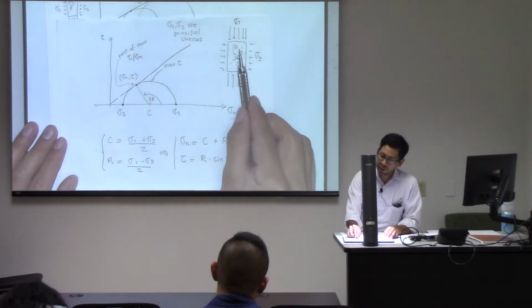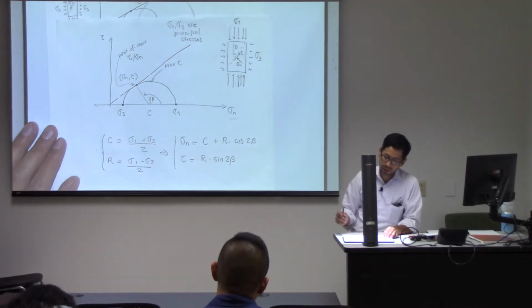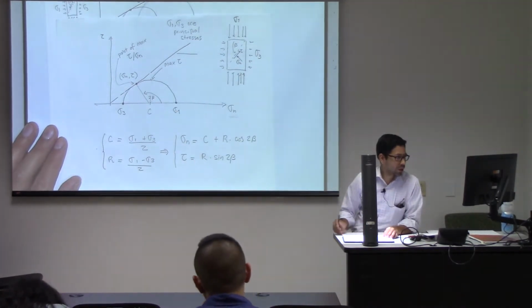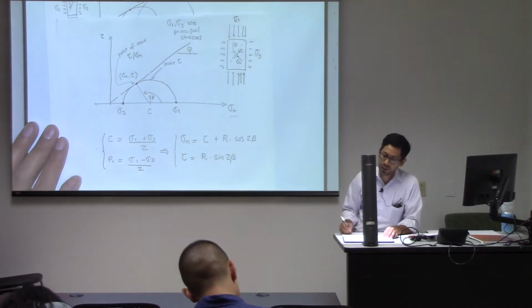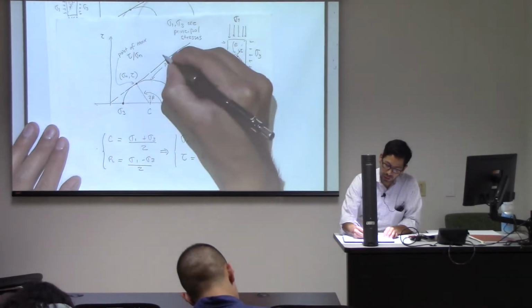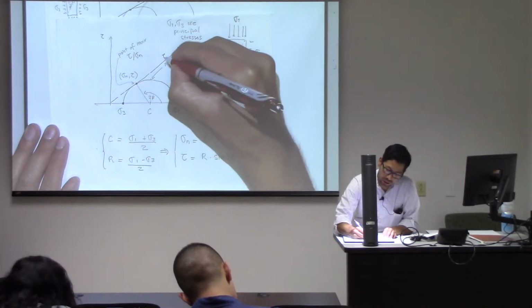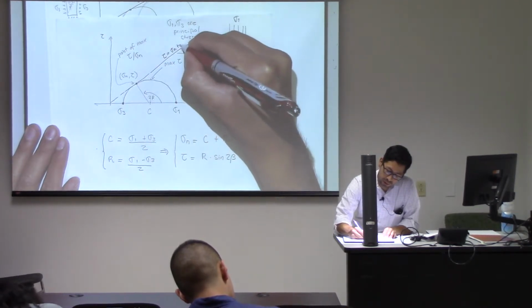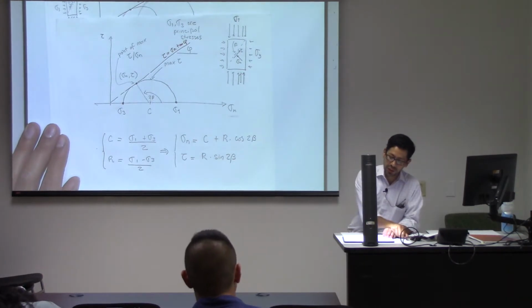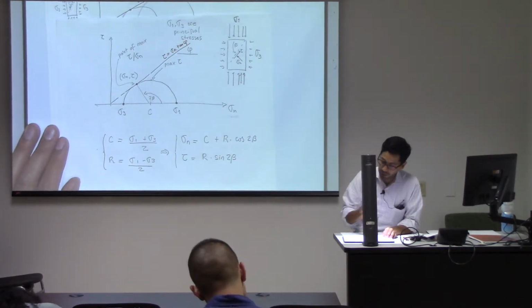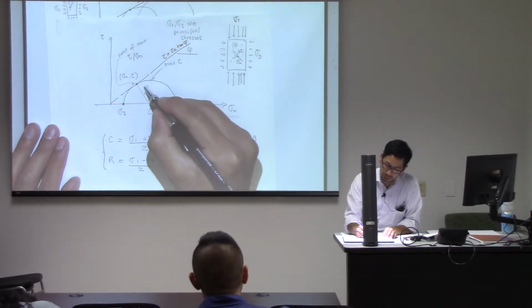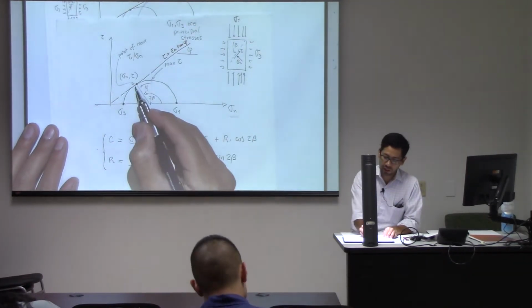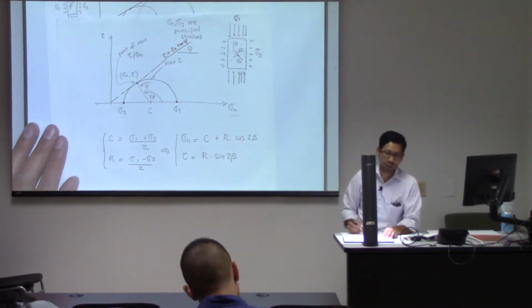So if you see the failure angle over here, you could do some trigonometry, and if this is the friction angle in which tau, the friction law, is sigma n times the tangent of the friction angle, which gives us a friction coefficient, you will see that also this one here, by trigonometry, is a friction coefficient if I take that point over there.